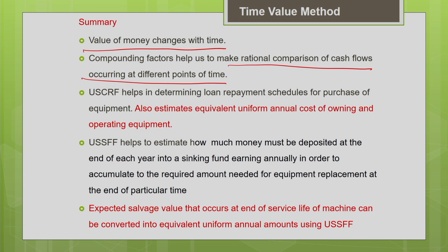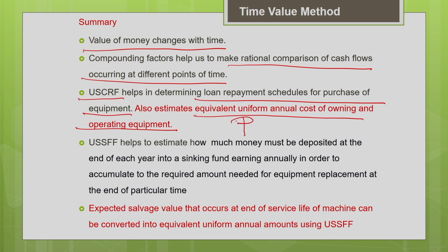Then we saw the application of the uniform series capital recovery factor. It helps in determining the loan repayment schedule for the purchase of the equipment. It helps you to determine at what rate you can recover the capital invested. Also it estimates the equivalent uniform annual cost of owning and operating equipment. It helps you to convert the present purchase price into annualized purchase price. That is how we estimated the depreciation in the time value method.